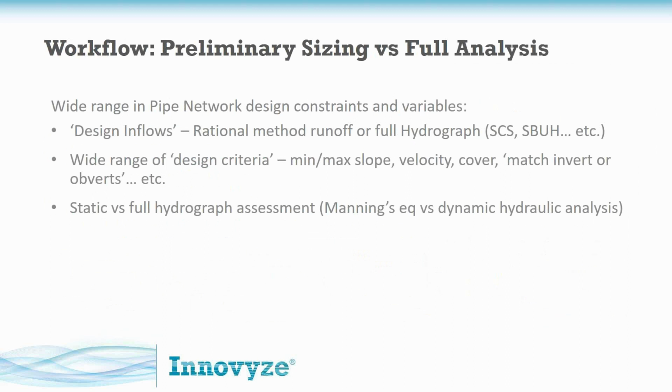The full dynamic hydraulic analysis is the other extreme. Perhaps I might refer to that more as the realistic. Again, it's a little made-up answer, but it's accommodating a full hydrograph in a complex site where the timing and the attenuation through facilities is going to be probably completely different than a static assessment would show.